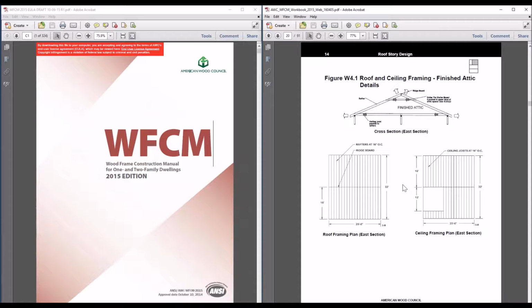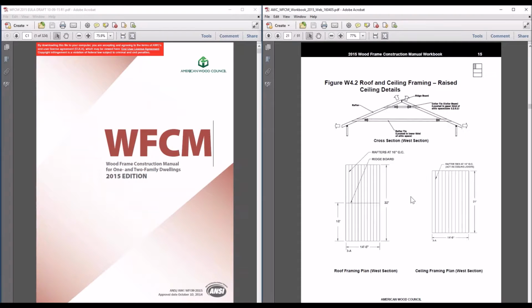And we're going to start at 16 inches on center and adjust as necessary if we need to. And so now jumping to page 15, you see a similar detail in the upper right, which means we're now looking at that vaulted ceiling. The difference here is this rafter tie is raised about 1/3 up into the attic space, and that's going to create some additional moment on these rafters that we need to account for. We can do that with the tables, and we'll talk about that.